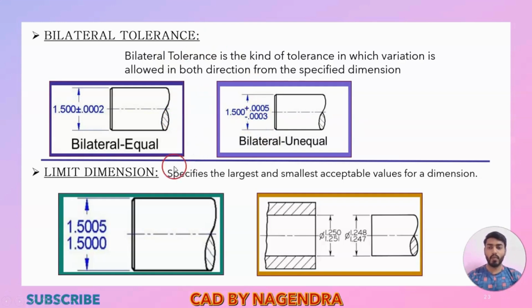Along with this, one more we have: limit dimension specifies the largest and smallest acceptable values for a dimension. Usually tolerance is mentioned separately with plus or minus, but with limit dimension, the tolerance value is added to the original dimension. We directly mention the maximum and minimum dimension sizes within which we need to get that part. So here tolerance is added to the main basic dimension and it is specified as the largest and smallest acceptable values for a dimension.